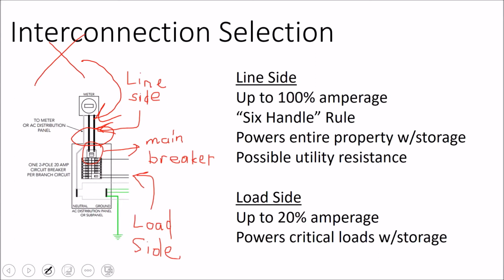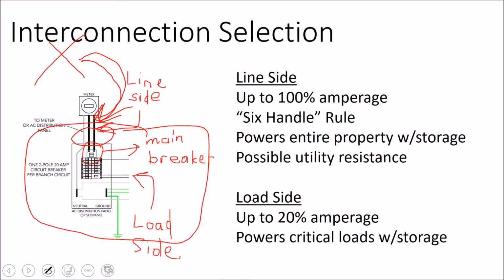And so let's turn the generator on until the batteries get up to 80% capacity, and then we'll turn the generator back off. That's one way to do it, but that's an expensive way to do it. Until batteries drop, you could do a line side connection and then just have the generator run the house during the power outage.